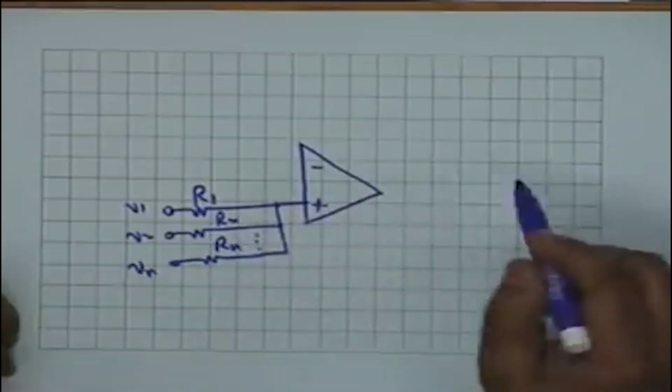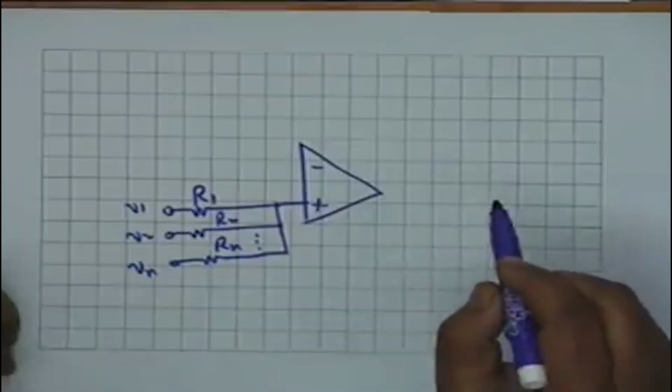Oh, I cannot do that, because an operational amplifier, because of the high gain, can never be left open circuited. Except in very special situations, we cannot leave it in an open loop. We will clarify this later in great detail: a high gain amplifier should always be operated with feedback, and feedback should be negative feedback.